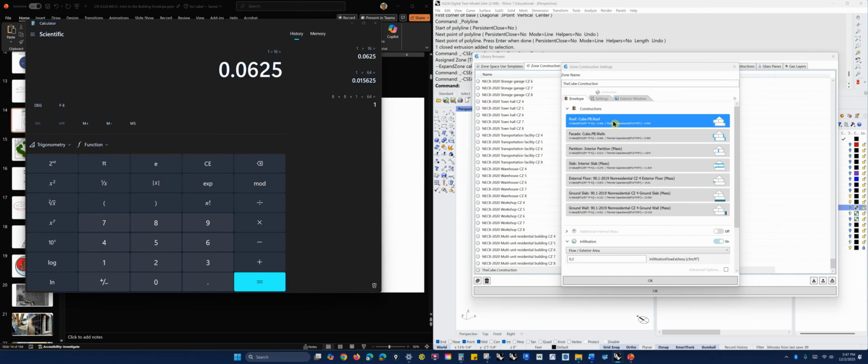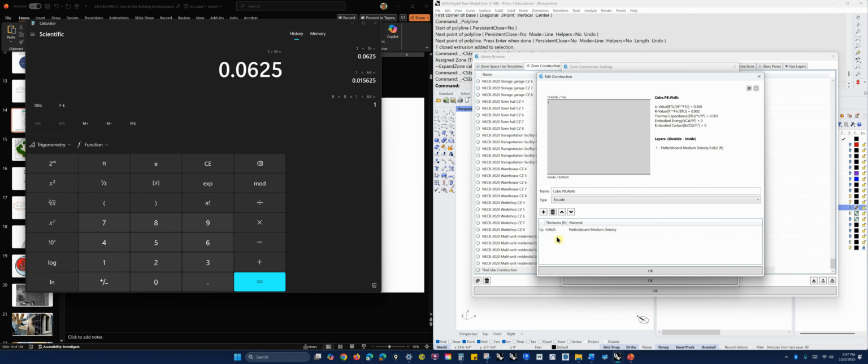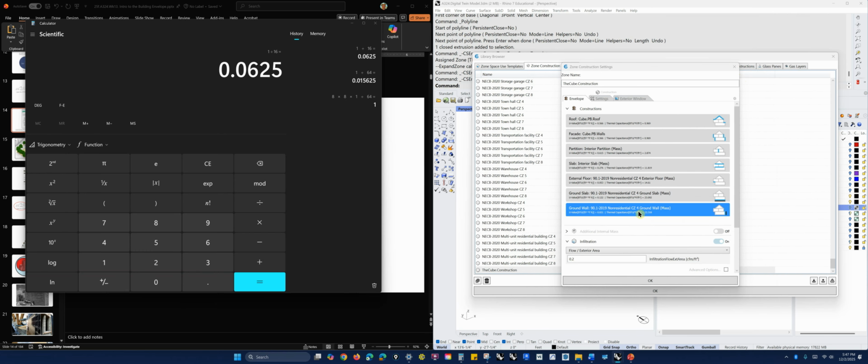I say OK, and now I've got a roof portion of my envelope that I can choose. I did the same thing for walls. I actually made it exactly the same, but I wanted to have 2 so that I could apply them in different conditions, walls and roofs. Okay, so that's the assembly of the envelope itself. We talked about what we have: liquid water, water vapor, heat, so thermal, and air. The only things that we're going to define in this model are heat and air.